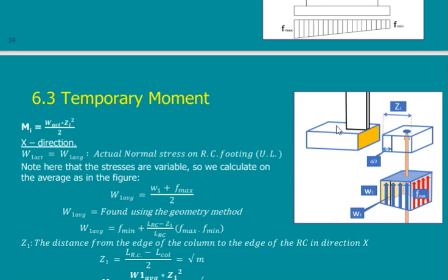Should I calculate the moment of the other cantilever? No. Why? Because it will be less. It may be less, and I would calculate it only to get the amount of steel. But here I don't have a separate amount of steel because the reinforcement will continue to the other side. So if I need here, say, 5 rebars per meter, phi 22, I cannot make them phi 16 in the other direction.